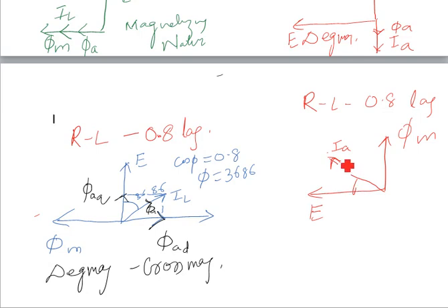So it has two components. This IA will have armature flux phi A. Again, if you see, one component will be in this direction, phi A. You can say this is D and this is Q, phi A Q. So phi A D magnetizes your main flux and phi AQ cross magnetizes your main flux.